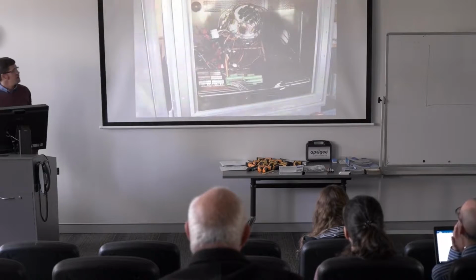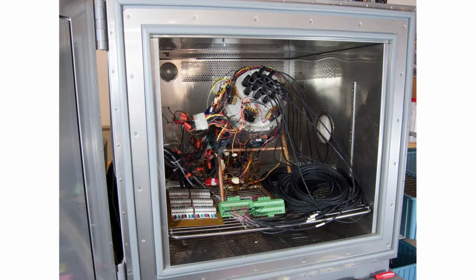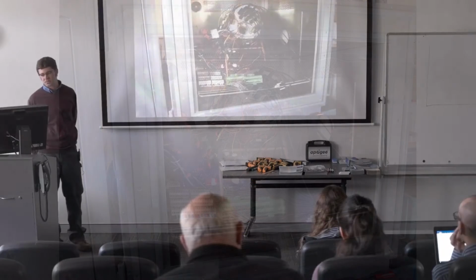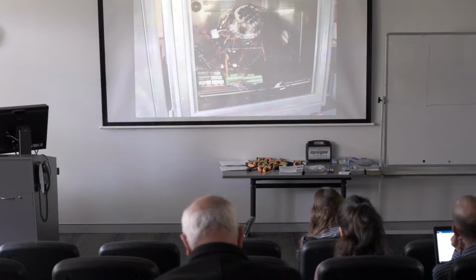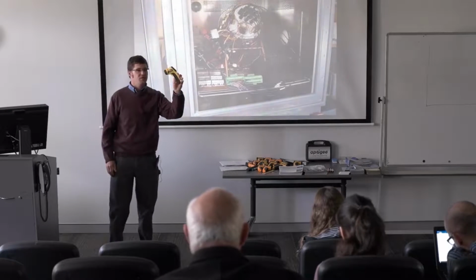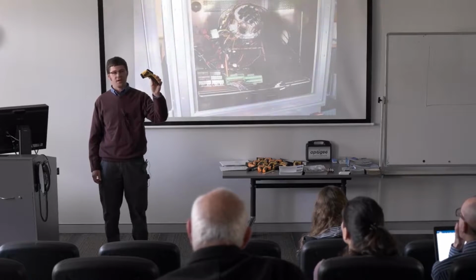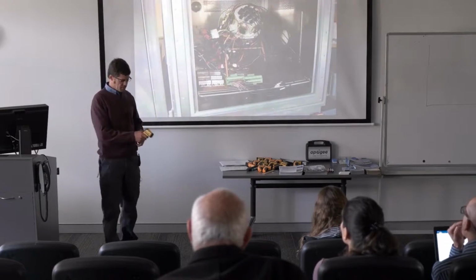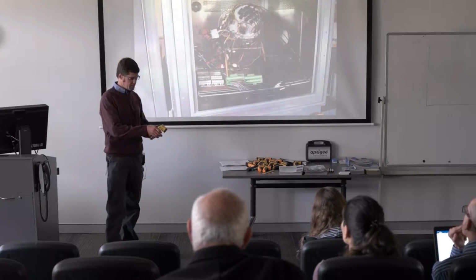So just to give you an idea of calibration, I got a couple quick pictures right here. This shows the calibration system that we use at Apogee Instruments to calibrate infrared radiometers. And there's lots of these things commercially available, and we're going to let you play around with some of these handheld devices later. You can get models like this really cheaply at the hardware store, and you point them at the surface that you want, you pull the trigger, and it gives you a temperature.